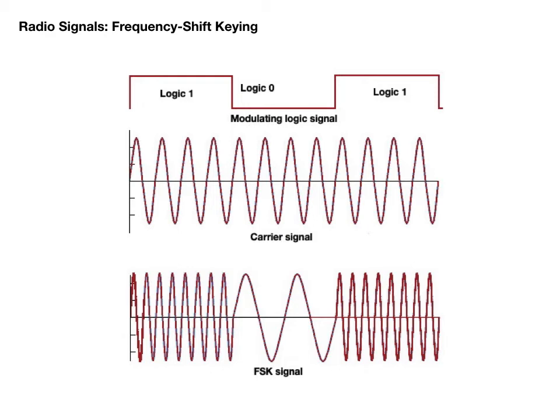To send radio teletype, a transmitter shifts the transmitted signal between the mark and space frequencies depending on the digital sequence to be sent. There are two ways to do this. The first is to actually shift the carrier frequency. The second is to set the transmitter to single sideband and shift the audio tone modulating the transmitter.